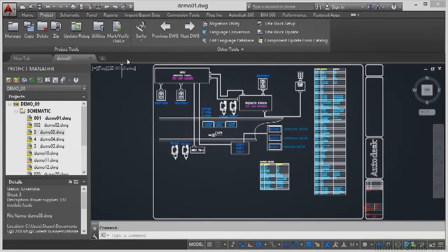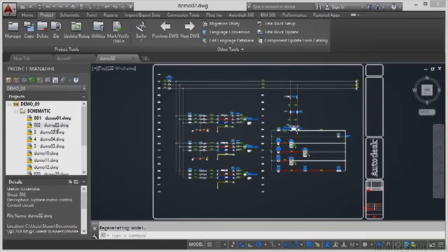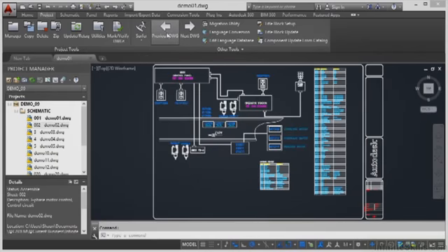And also you don't want loads of tabs, 20, 30 tabs across the top. Maybe a couple, so I might open up 1 and 2 like that. That's not going to slow my AutoCAD down. Try and keep this to an optimum amount of drawings and use the next drawing and the previous drawing. If I do this now, you'll see that if I go back there, even with that drawing open, it closes Demo 02 and goes back to Demo 01 in the list, and I've just got the 1 tab left. So it is the quickest way to use those arrows to navigate and move around between your drawings in your drawing list in the project manager in AutoCAD Electrical.